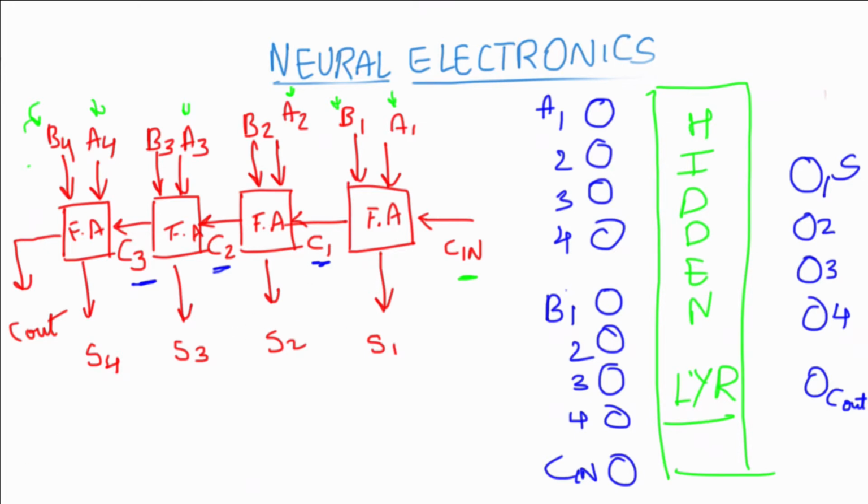If you take this network into consideration, the computation time is directly dependent on the number of calculations that you need to do per full bit add. Let's say, it's totally absurd, but let's say you take 1 second to do a calculation in a full bit adder. So the first two bits over here will go into a full bit adder and take a computation time of 1 second, and will give you the output into S1 and C1.